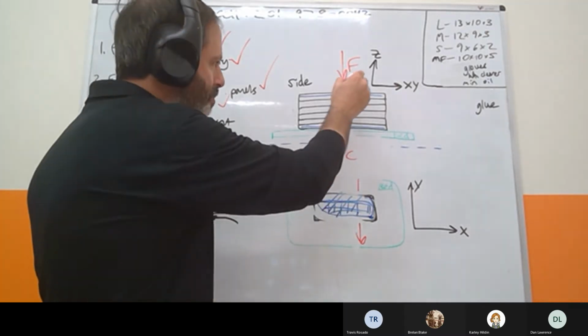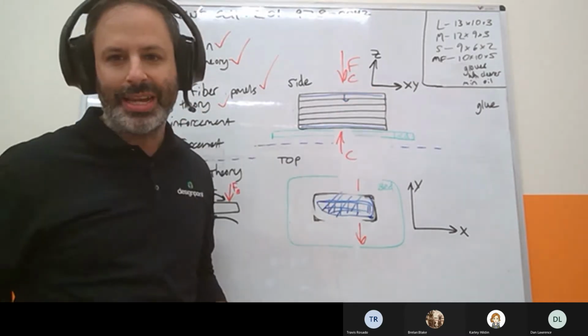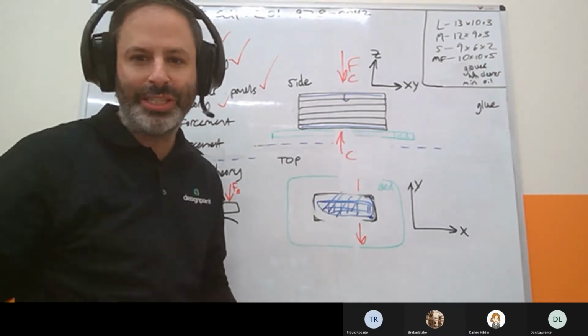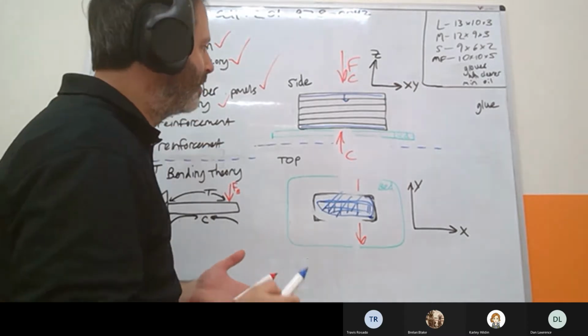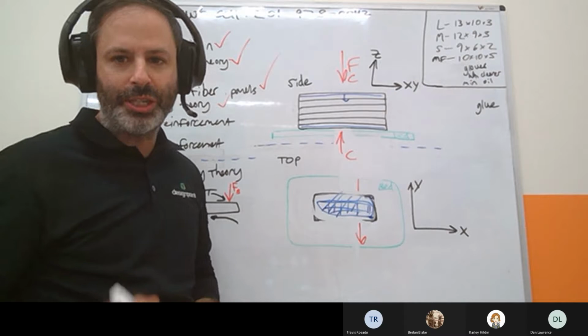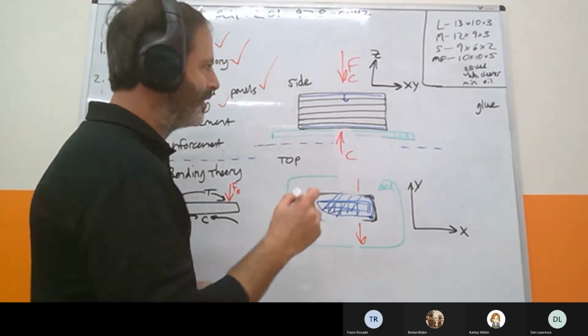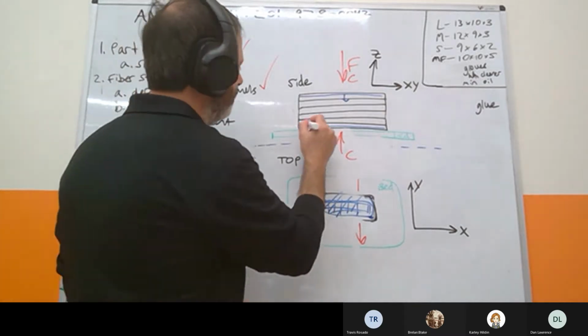Because it's simply going to push this panel down into the weaker plastic, and it's just going to fail by transferring the load to the weakest point. So the strategy you use when reinforcing for compression is called stacked fiber, okay?